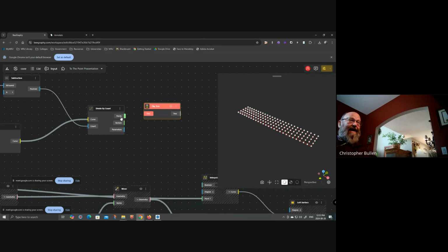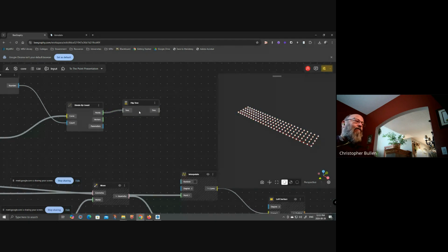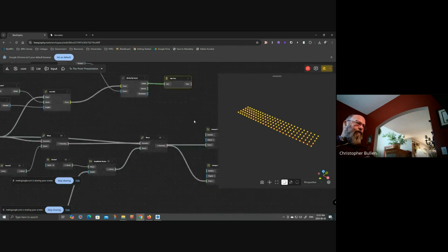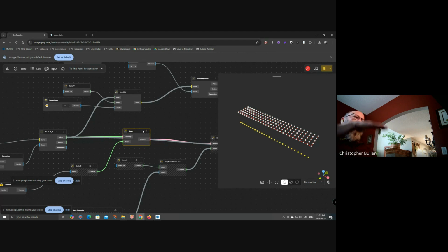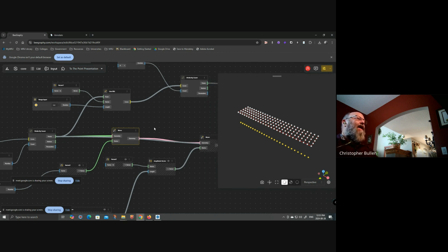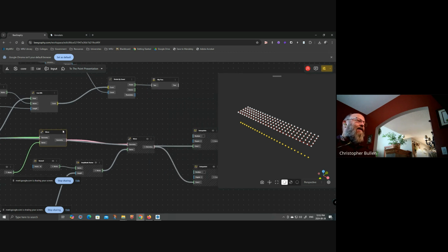So we're going to take this list of lists, which right now, as we can see, is 27 lists of 5 items. When we plumb that into here, this is now 5 lists of 27 items. So now we've transformed the data so that we can interpolate those points. Now that we have all of these points, remember what this one here did. This one moved all of those points down, right? Well, we're not taking these anymore. Let's take all of these and move them down.